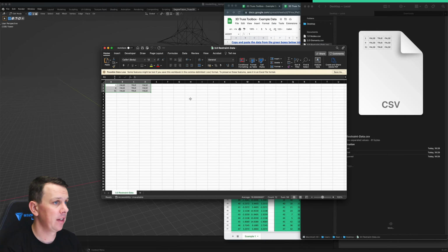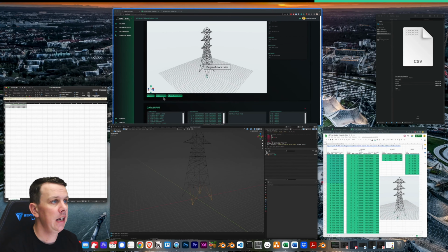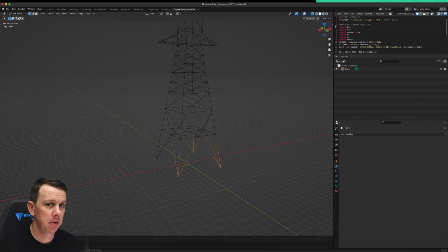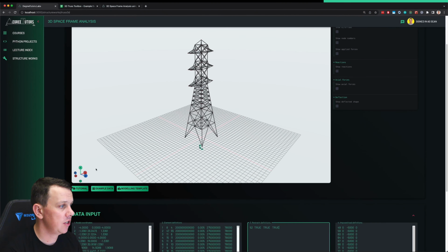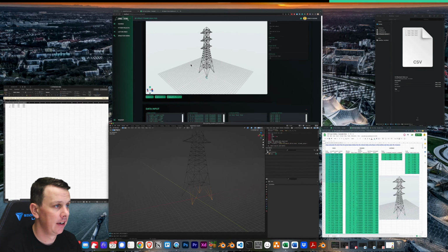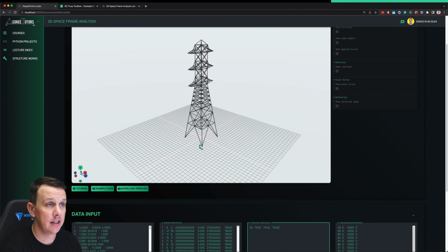Now you'll notice that there's a little quirk here, right? Blender is kind of peculiar, well, I guess it's not peculiar in the artistic 3D world, but Z is up in Blender, whereas in a lot of other applications it's Y up, right? The Y axis is up. Now, you don't need to worry about that. You just obey Blender when you're in Blender and obey this coordinate system when you're over here. I've taken care of the translation between the two, just basically swapping the Y and Z coordinates in the back end in the code. You don't need to worry about that.